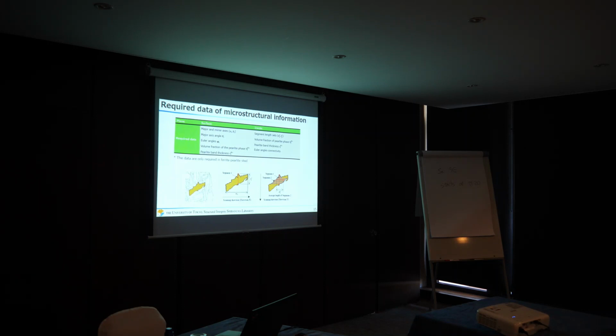Yeah, that's exactly the point. So you measure the distance in the horizontal and vertical direction, but is it the relevant distance for this particular grain at 45 degrees? Yes, actually the crack can propagate in this direction or this direction, or any direction is possible. But considering the distribution of the grain boundary length, we can measure it from any direction.